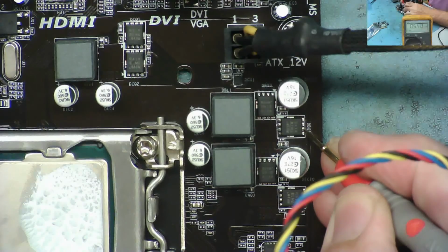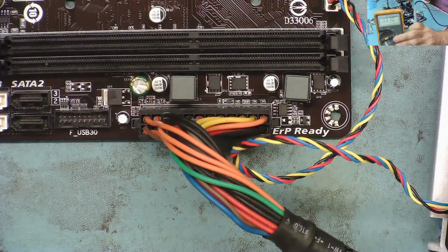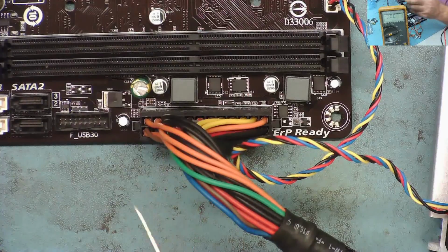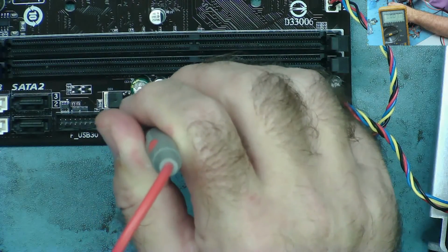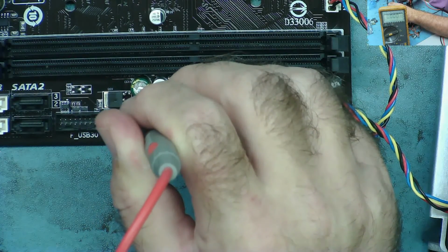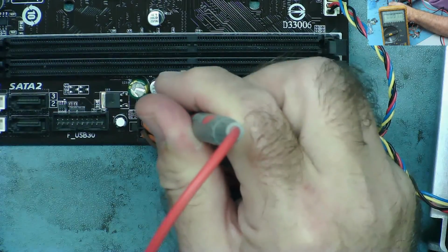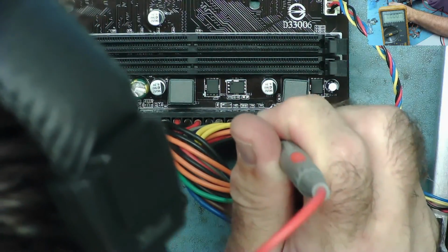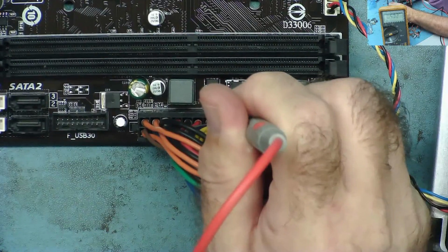Well, that's interesting, because the power supply seems to be switching on and off. So let's go over to the ATX connector and see what's happening with the other voltage rails. I'm guessing they're going to be doing the same. So this is the 3.3 volts, and it's powering on and off. Red will be 5 volts, powering on and off. Yellow, 12 volts, powering on and off.